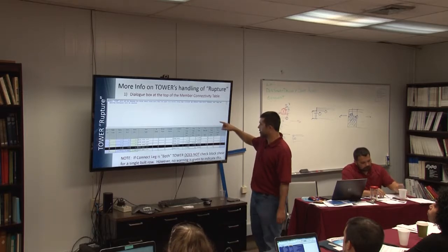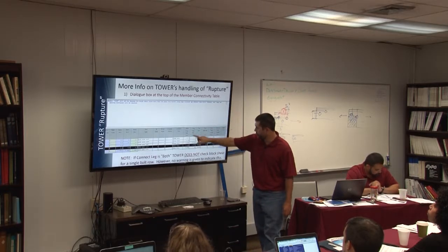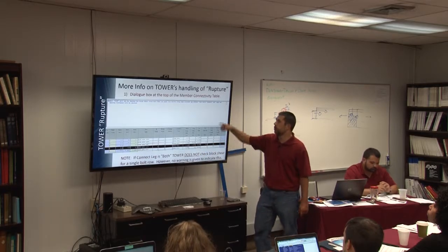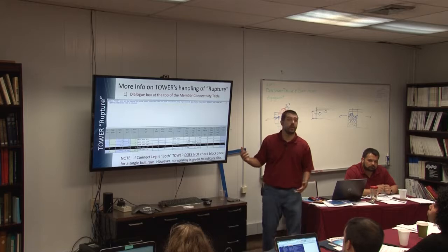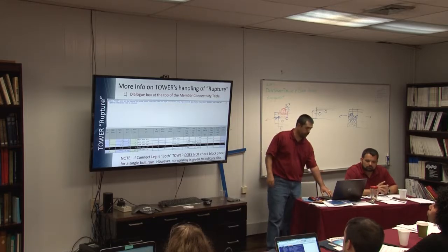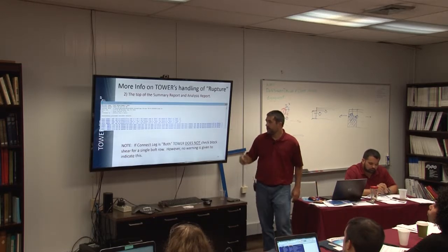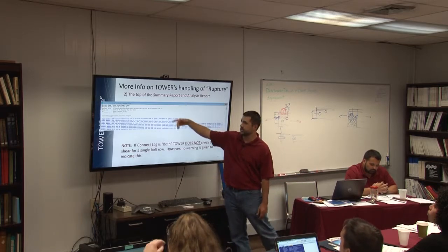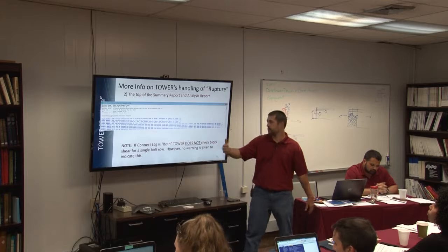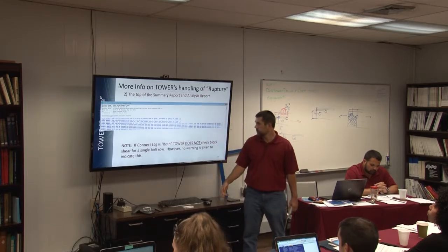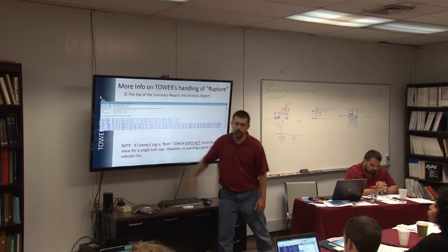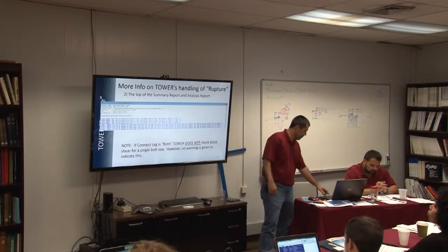So the idea here is that there's more than one gauge line, but they have an input shear and tension path lengths. So it'll throw a warning to say, block shear is not being checked for this member. Be aware of that. That same warning will show up on your output report. So this is like a result. When you run an analysis, you get a list of warnings, and it will give that same warning at the beginning of your output reports.